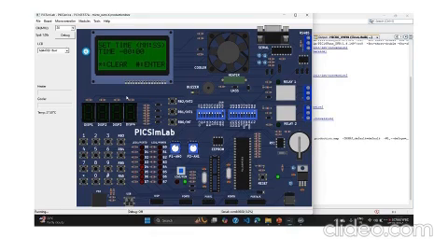Micro mode. 900 watts is the maximum power. You can set the time here. I'm setting the time to 10 seconds. Star is for clear, hash is for enter. I'm entering. You can observe here the fan is rotating when I entered it. Here it is indicating the heating. After time is up, the buzzer will indicate the signal.